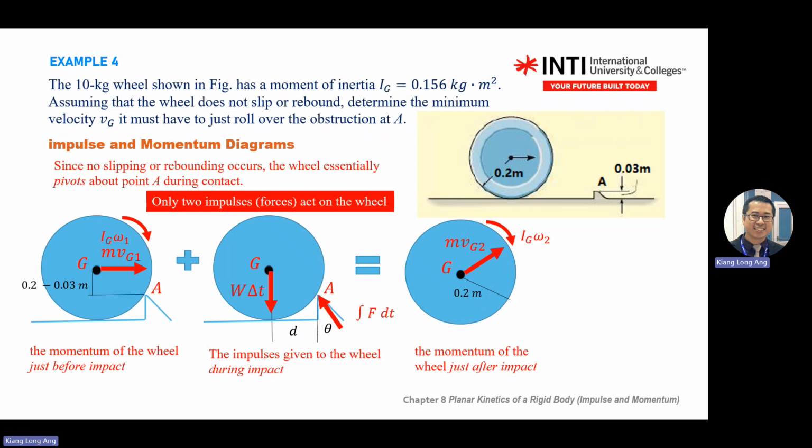Because this is rotation, you have an omega factor and inertial factor. Okay, so practice more on this kind of example. As you practice more, it becomes a habit. You will know what to write in the three diagrams. First diagram is all the force converted to momentum. The first diagram is on the velocity. Where is the velocity acting? On the center of mass.